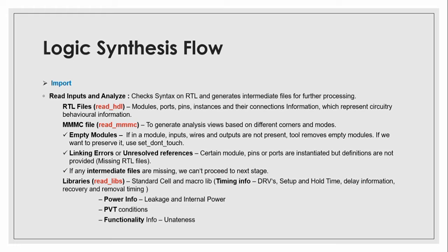This can happen when we start the synthesis flow while the RTL design team is still making the RTL files. They may have just instantiated modules and handed them over to us so that we don't waste our time. At that time we may see certain empty modules reported in the log file.